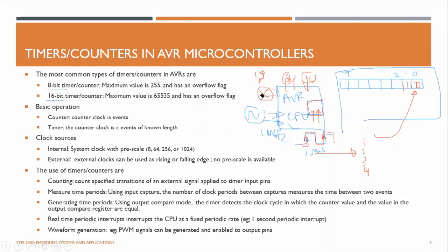Instead of that, we can blink this LED by using a timer. Timer means you set this timer to, okay, I want every 1 second, give me a signal when this is ready, right? So every 1 second, it will give a signal to the CPU, okay, it is a 1 second time. And in the next cycle, it again says to the CPU, okay, the next 1 second.